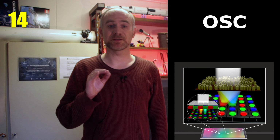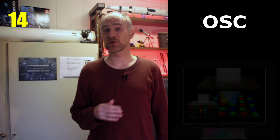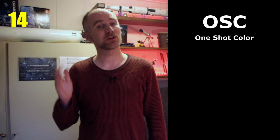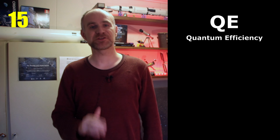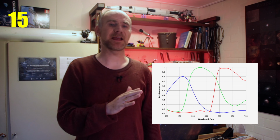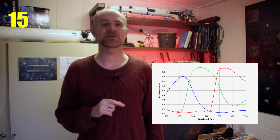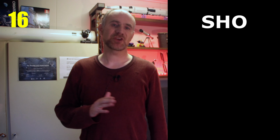OSC is in theory a mono camera with a specific filter array called a Bayer matrix in front of the sensor, and that way the camera turns into a one-shot color camera. QE is the quantum efficiency, basically the ratio of photons that actually succeed in getting registered by the sensor. You'll see this mentioned on websites selling astrophotography cameras.